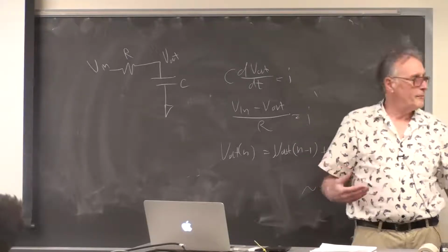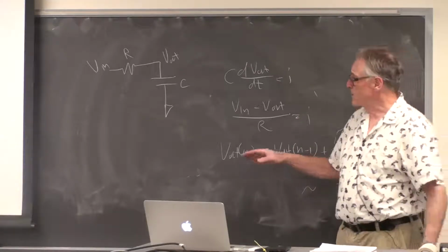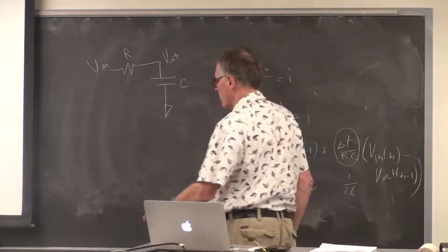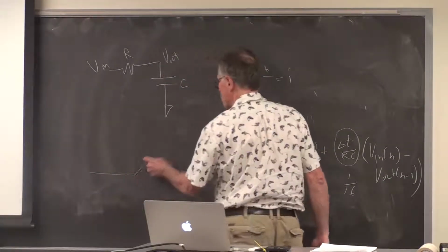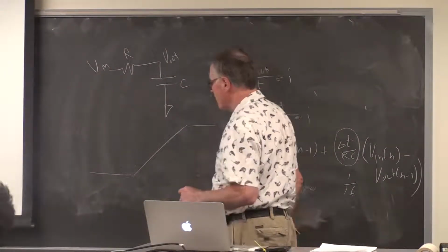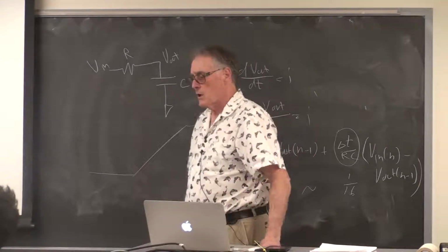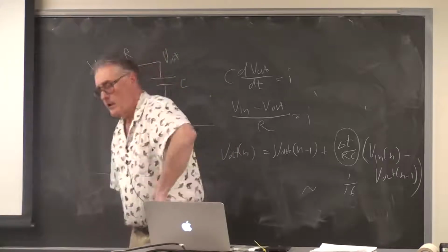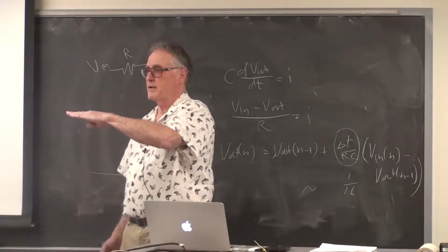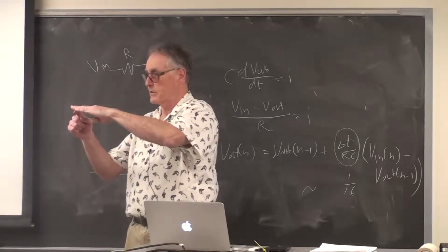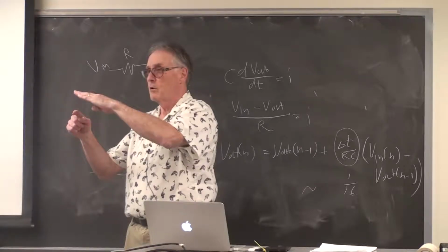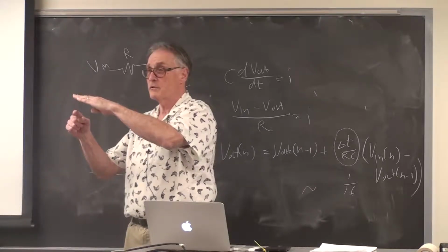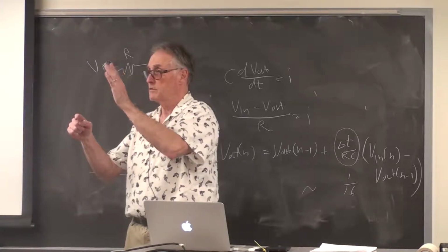You have to make sure that you saturate the control algorithm so the PID can never go below 0, can never go above 40,000. So whenever you overshoot the angle, whenever this thing comes swinging up and goes past the desired angle, the motor just shuts off. It doesn't slow down, it's just off. Goes to 0.